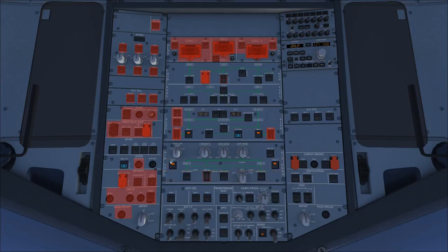At the moment they're showing as a fault because they work by taking pressurized air from the engine. That's why they're showing as a fault at the moment, because the engines are not running. In the top left you have a knob which controls how the speed of how the PACs work between low, normal and high. So you may find that some airlines switch to a low setting because it improves the performance of the engines.